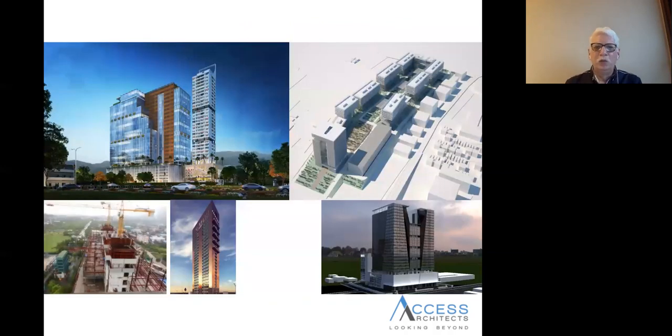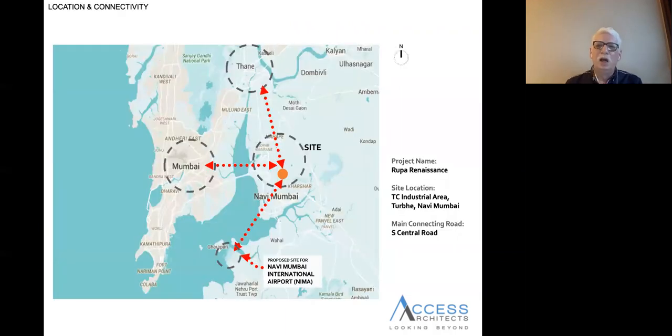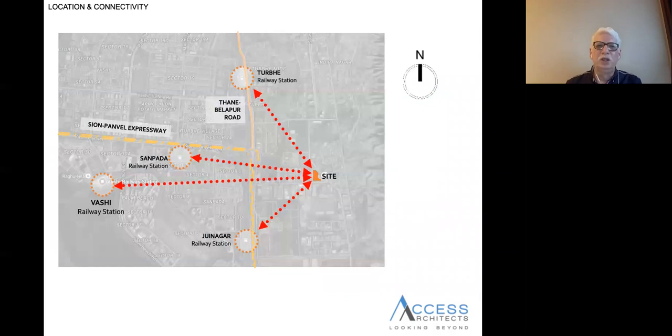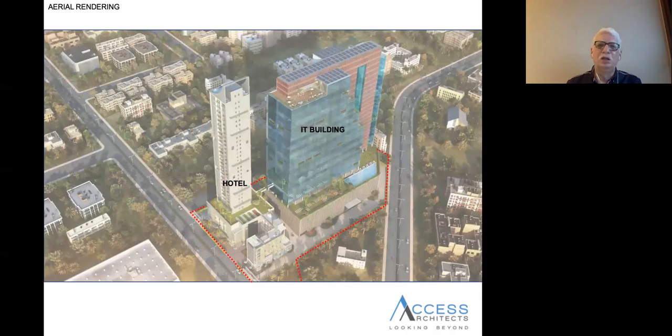What we would like to also show you is the difference in terms of technologies and how the facade makes a difference in terms of the technology. So in the steel composite building, the way facade is installed vis-a-vis in a concrete building, there is a difference in terms of the installation detail. One needs to ensure that you use a proper smoke seal, which is detailed out differently. So between the slab, there is a smoke seal which you would ensure that the smoke doesn't pass from lower floor to the upper floor.